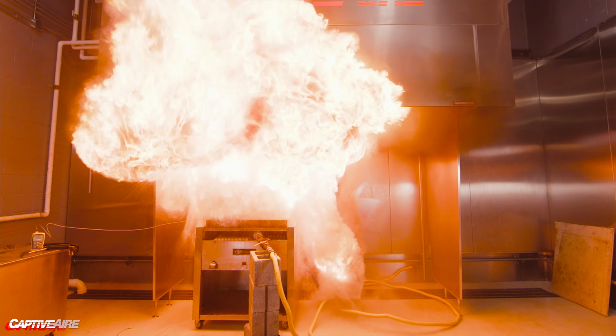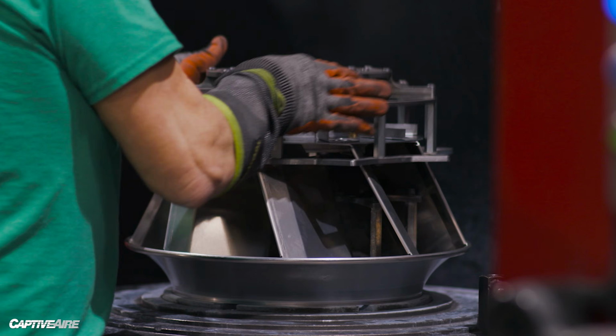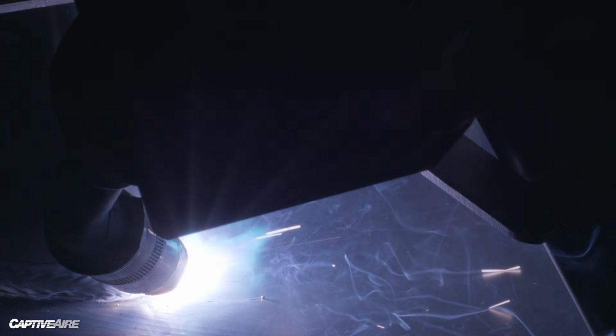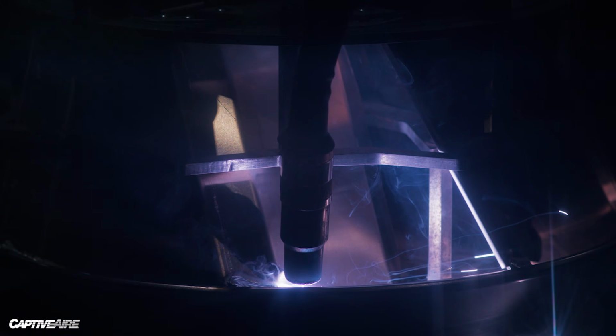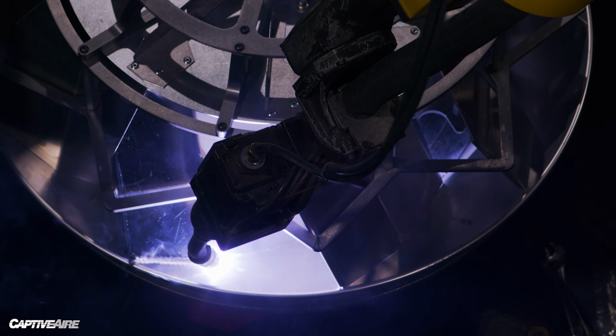The temperature also is a big factor, and one of the reasons that we don't use prop fans for grease applications. Static pressure is one thing, but also as you start to increase your temperature, the wheel itself has to be made out of certain metals and be structural. When you weld together our centrifugal or mixed flow wheels, they're very strong, so they can handle very high RPMs. And then once you start to bring temperatures into it, you have to make sure that the wheel can sustain those RPMs without failing.